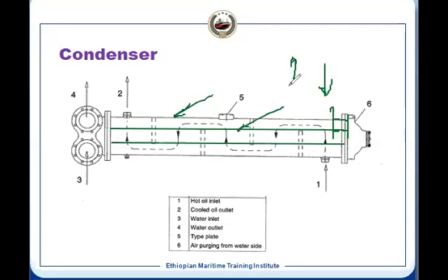Now, as I told you, we choose the material design in such a way that the differential thermal expansion is not there. Then, suppose on the base we have a bolt which is securing. That bolt will have a hole, and on one end we keep the hole open. Then it can take that thermal expansion, and it will be the total thermal expansion, not the differential. It means both will expand slightly because we keep the material design such that the thermal expansion is minimal. We can use a certain allowance to make that possible.